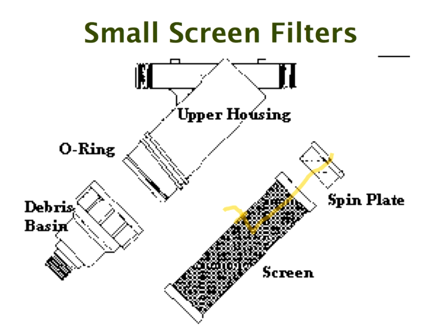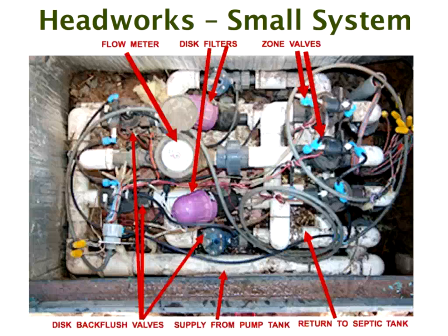So in order to prevent that from happening, you need to flush very, very regularly, and you want the pressure drop across the filter, across the screen, to be certainly less than 3 psi and probably even less than 2 psi to minimize that problem. But if it's used correctly, designed correctly, it works, which is true of all the filters we're talking about.